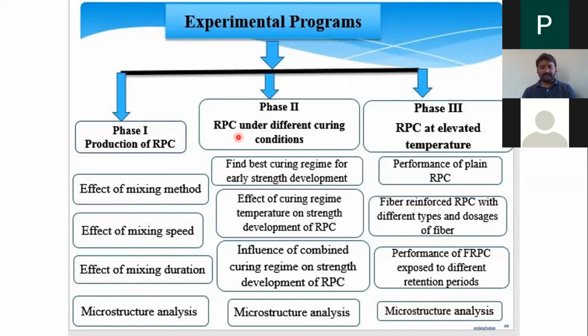So after mixing, once we produce reactive powder concrete, we have to get the highest strength. We have used different curing conditions, different heat curings, so that we find which combination will give us the highest strength. That also we have studied, so we'll discuss them.